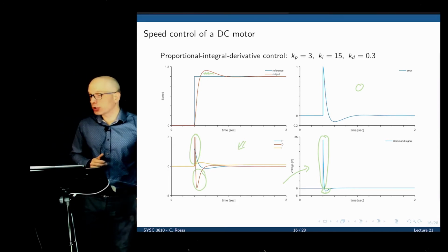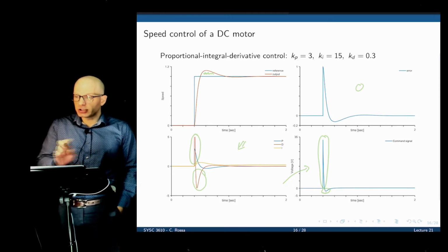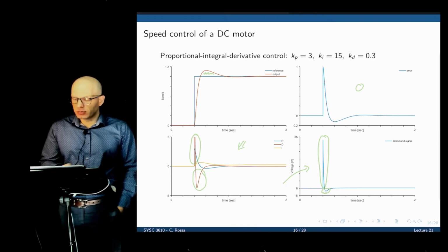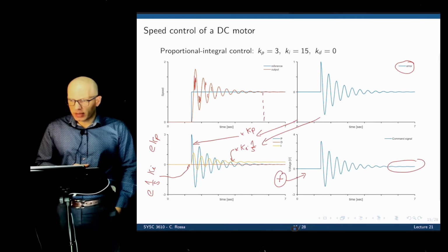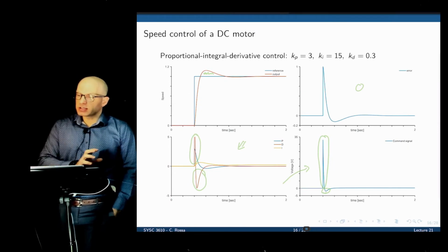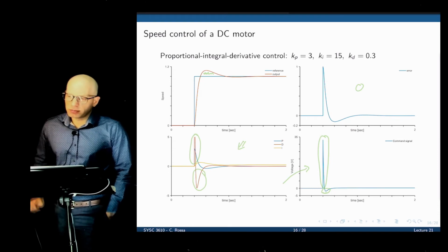And that's why it's important to have an accurate model. In some plants, you cannot afford to physically go there and change the PID gains and see what happens. Right? It could lead to some damage in the plant if you have this much oscillation, for example. So that's why with a model, we can analyze the behavior for different conditions, and then once we are sure, apply that to the plant.